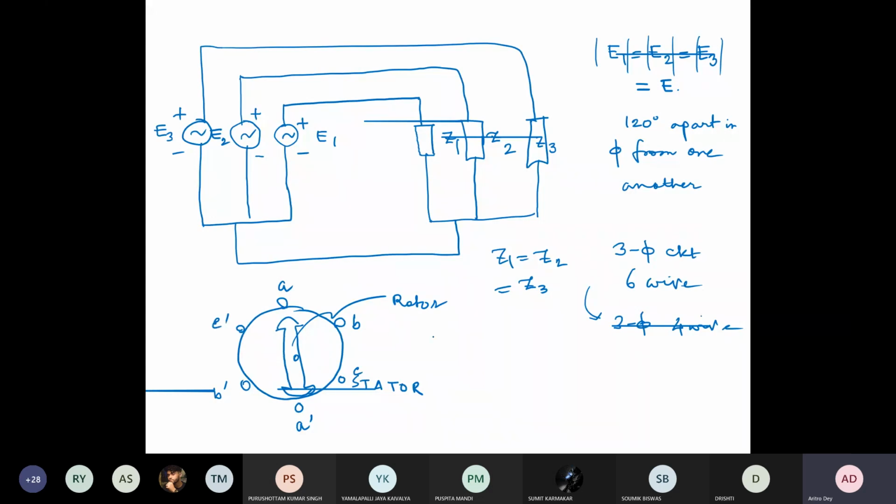So what happens when the coil at A at a certain point, you will be having your maximum field strength. So the flux lines will cut maximum linkage with the A dash coil. So at that time it will develop a waveform like this. This is your E A. Okay, so let us revise the drawing, and let me draw once again. This is your armature for the alternator, and this is your field circuit.